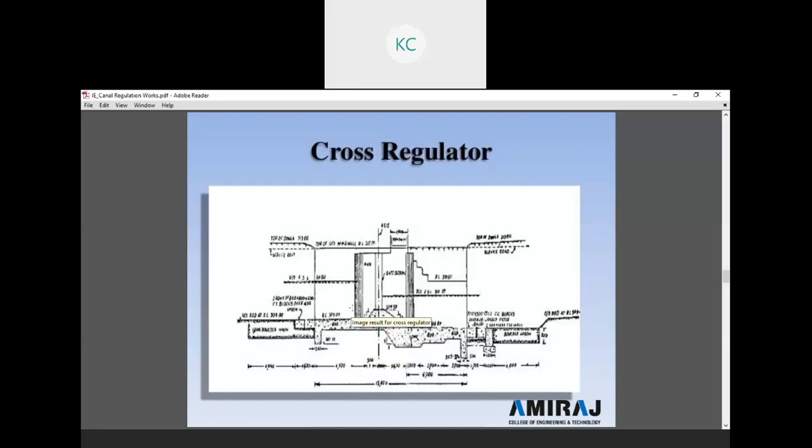So what are the piping and undermining effects? Excessive water percolates from the upstream side, travels beneath the impervious strata and washes out on the downstream side. So it will cause a damaging effect on the downstream side as well as on the lining or the surface of the canal. So to minimize piping and undermining action, the impervious floor is provided.